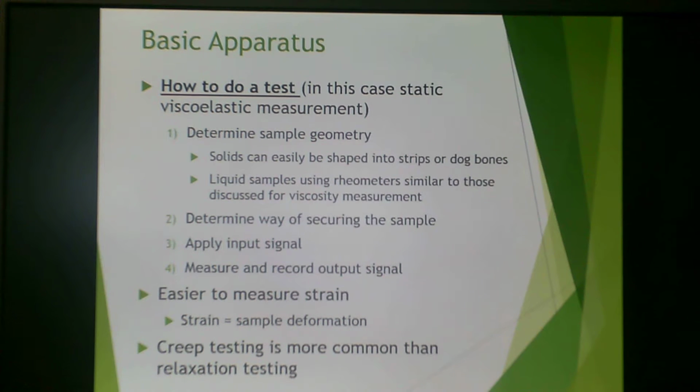It is easier to measure strain. Strain is where you're deforming a sample, and that's easier to measure. Creep testing is much more common than relaxation testing. In relaxation testing, you'd be measuring the stress, and that's harder to do.